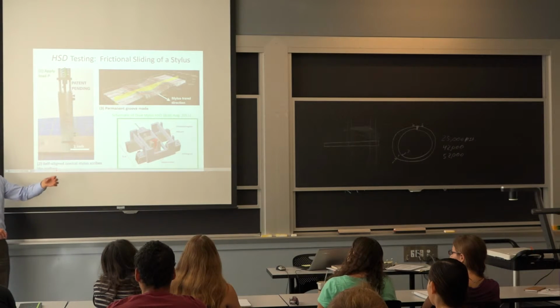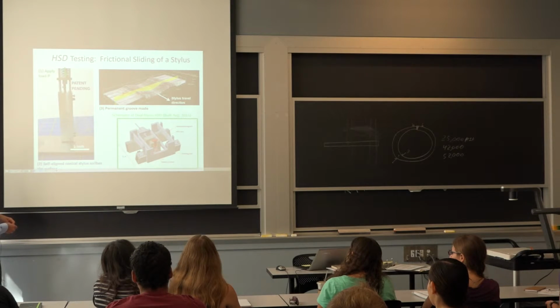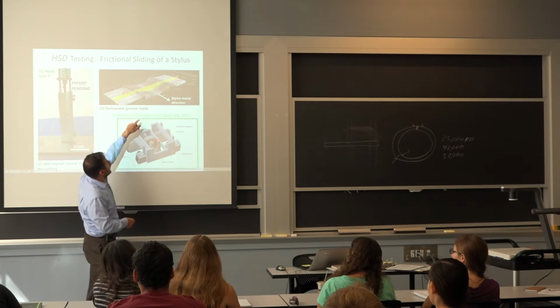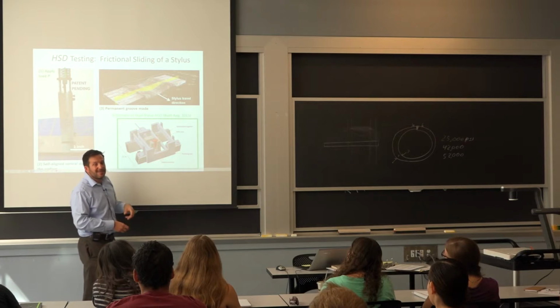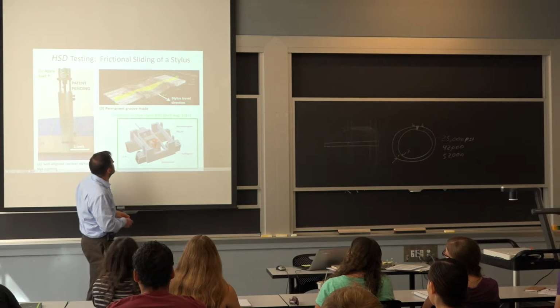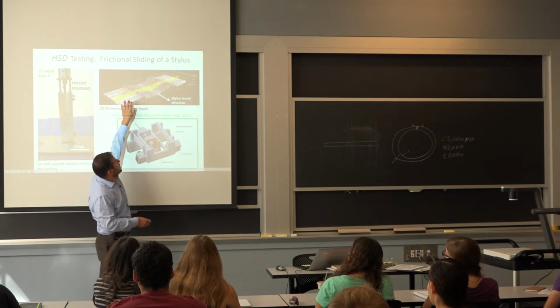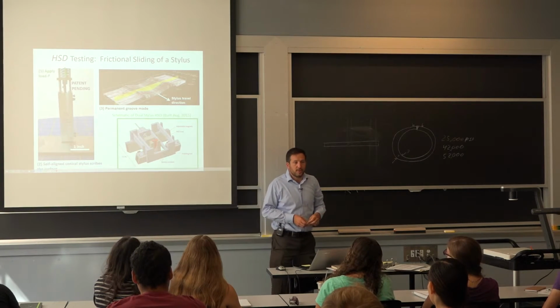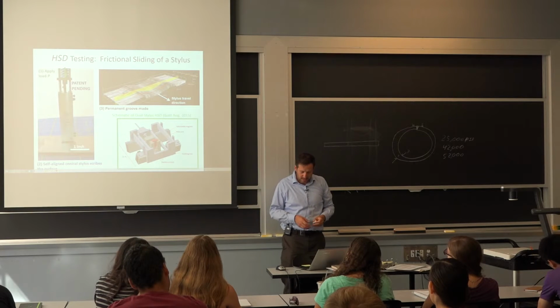That's very useful if you try to go around a pipe. And it creates this groove profile that's very shallow. It's only about 30 micrometers in depth, so it's not destructive at all to the metal. And we collect the information from that profile to back calculate the entire stress-strain curve. And we could go through more details of that.